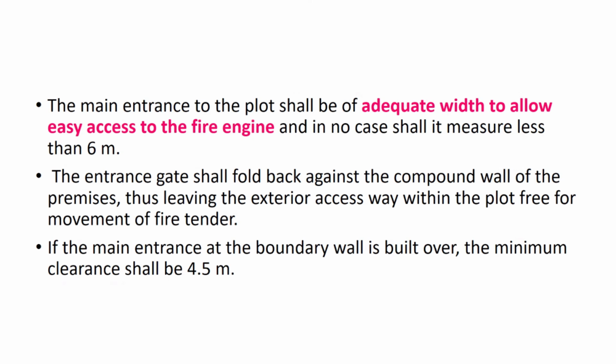Foundations have been erected based on whatever data they have had, and they are facing problems once the building has come up. The building is sinking even after 2 years in certain cases. Please mind well, subsoil investigations are required to be done very carefully, or rather more attention is required to the person, the contractor who is doing all these activities. Please see whether he is taking the borehole samples properly or not, because based on those samples, laboratory tests will be done and certain inferences will be drawn.